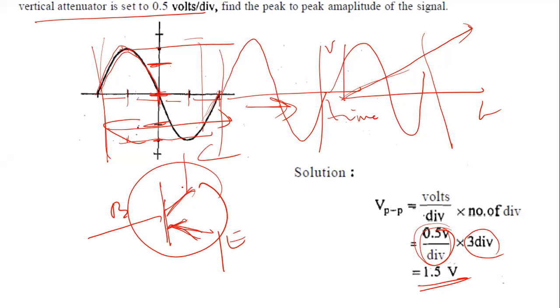And in order to operate this transistor, you need to provide a certain kind of fixed biasing. Fixed biasing means the DC voltage given between emitter and base should be fixed. And also the biasing between your collector junction and the base should be fixed. So in an RC coupled amplifier, you need a constant voltage to properly bias your transistor.